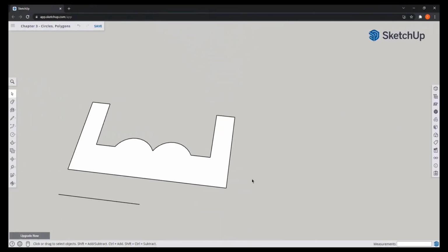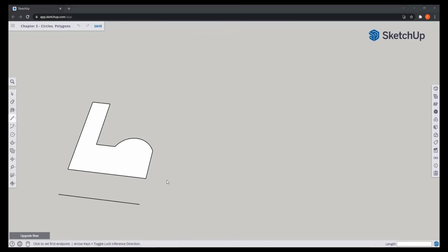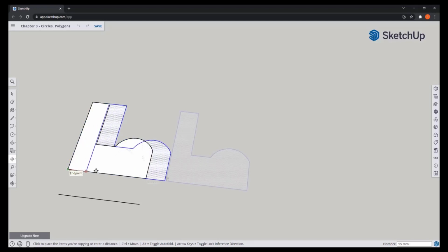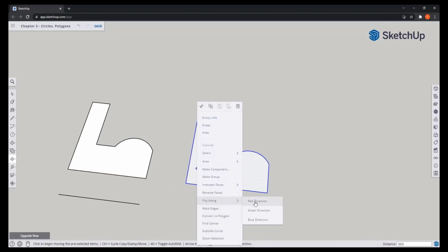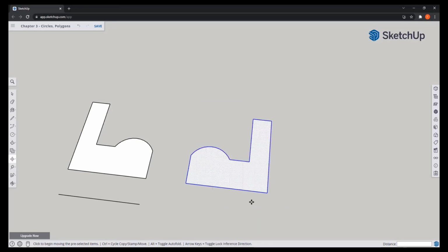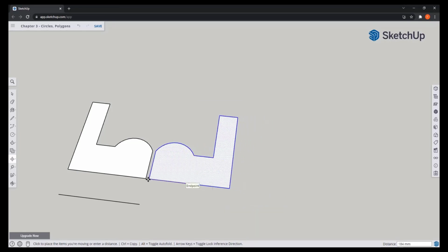Okay, I want to show you a tip. Let's learn how to make a symmetric drawing by using only half of it. So in this situation, I can copy these objects to the right, click in this point, move along the horizontal direction, and place them here. Then apply Flip, move from the corner to intersect the first drawing. Then I just need to delete the line separating the 2 figures, as both faces merge.